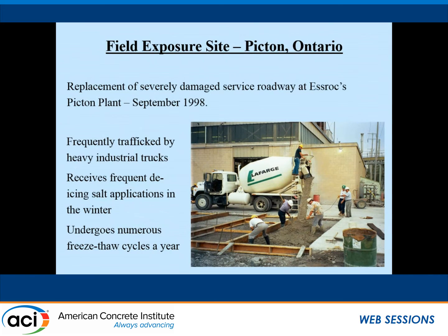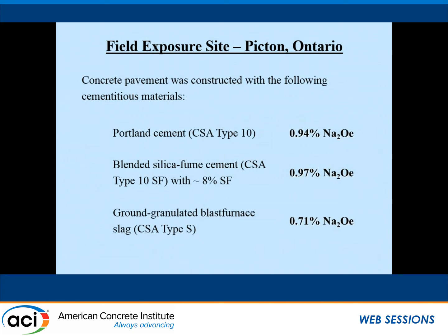I'll show you the details of some of the mixes. This is all trafficked concrete. It's trafficked by cement trucks every day. Frequent applications of de-icing salt. So we were interested in both the de-icing salt durability and also ASR. We deliberately used a highly reactive aggregate in this concrete.